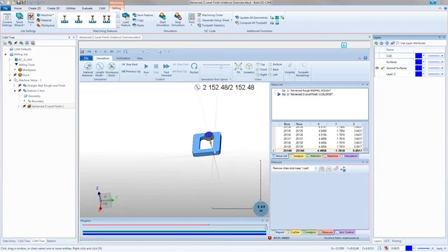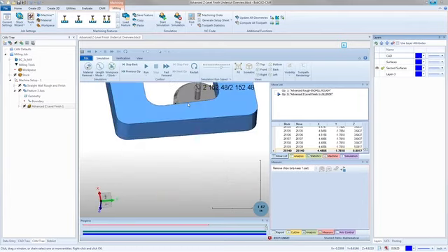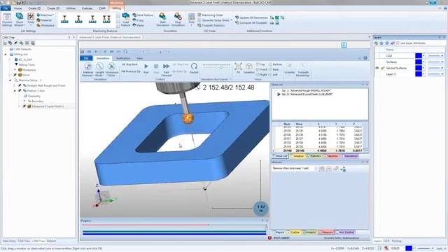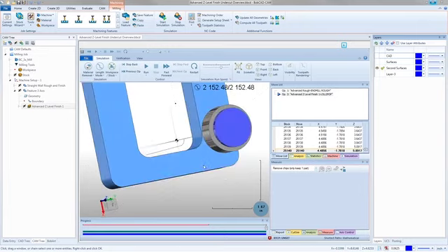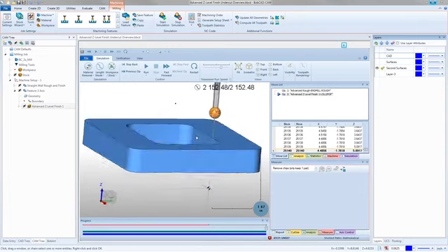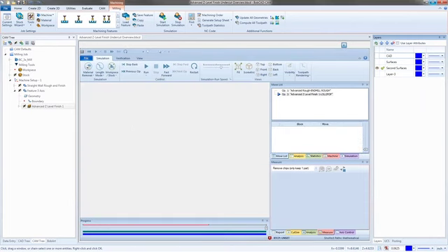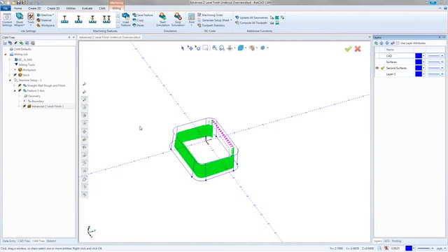So right there, you got your now undercut part without having to flip it over. So we got this job done in a one-op kind of part. There it is. This is pretty advanced, doing lollipop cutting and all this kind of stuff, but definitely some very, very cool functions that you can get into with it. So being able to do undercuts is a big deal. So that's pretty much all I got.